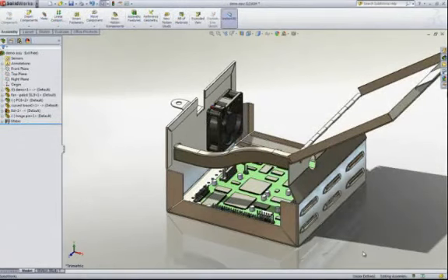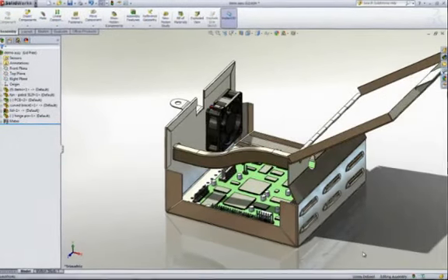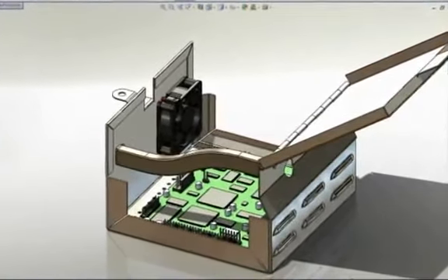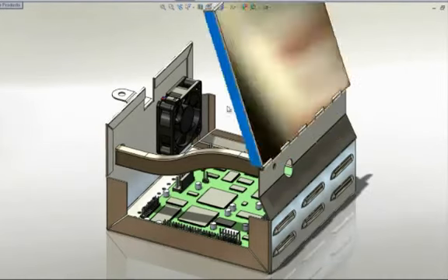Layers are automatically created for up bends, down bends, and blank size to properly communicate your part to the fabricator. Sheet metal parts rarely exist on their own, so a fully featured, robust assembly environment is a must. In this SolidWorks assembly, there are a couple of components that need to match the size of our box.